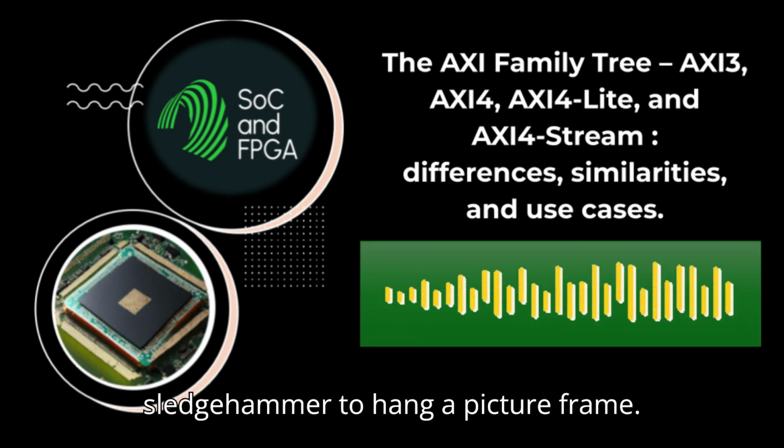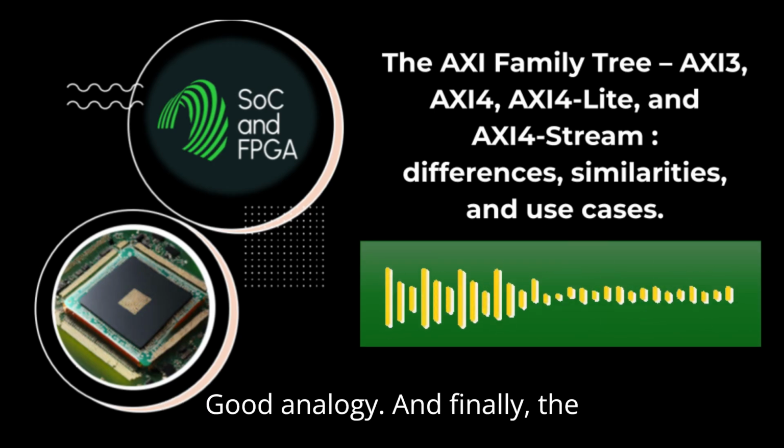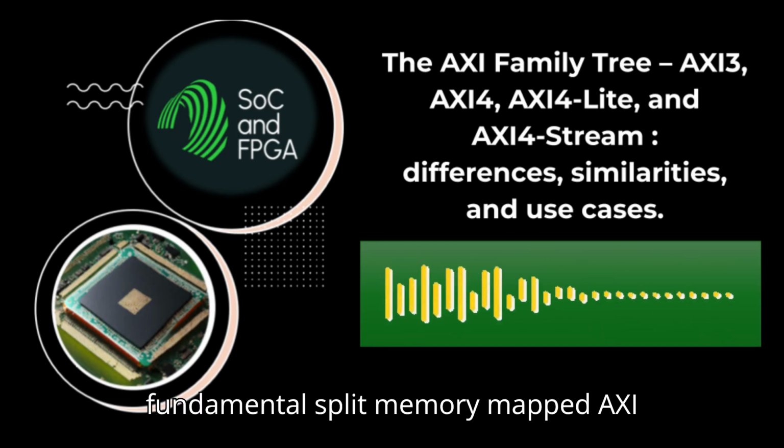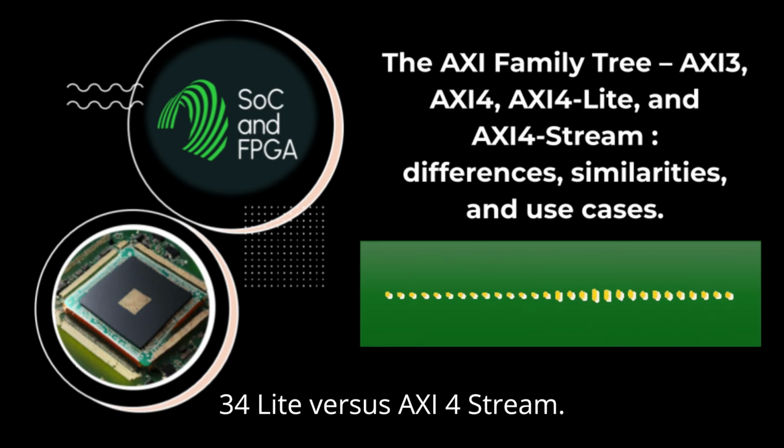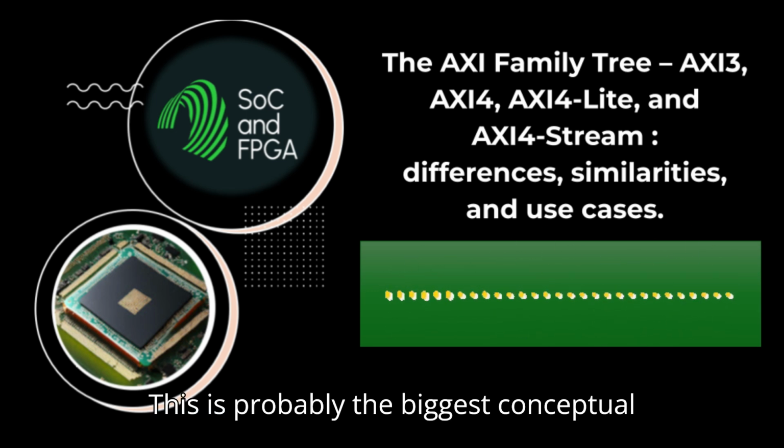You wouldn't use a sledgehammer to hang a picture frame. Good analogy. And finally, the fundamental split: memory-mapped AXI4 and AXI4-Lite versus AXI4-Stream. This is probably the biggest conceptual divide.